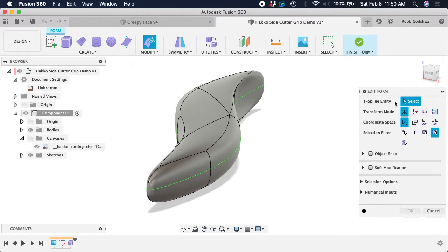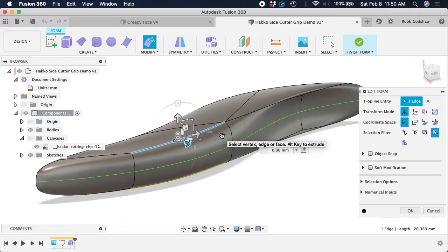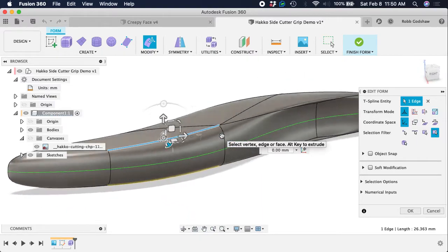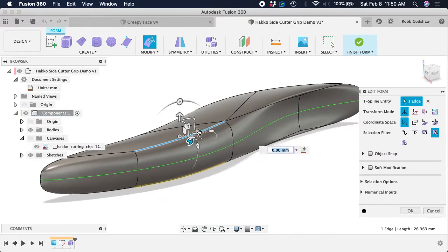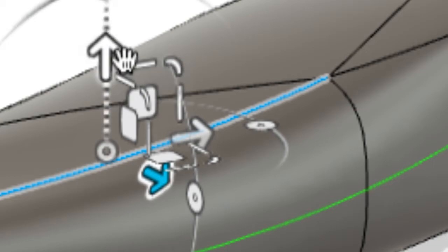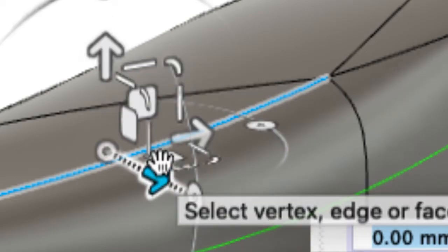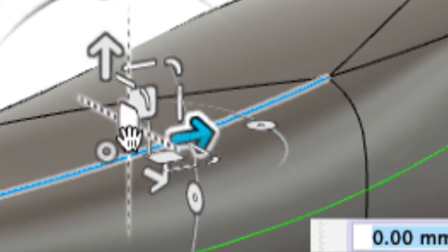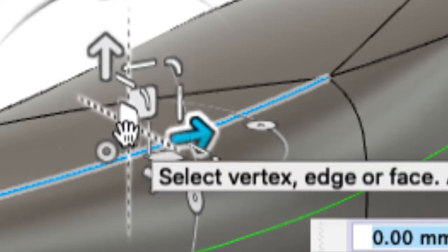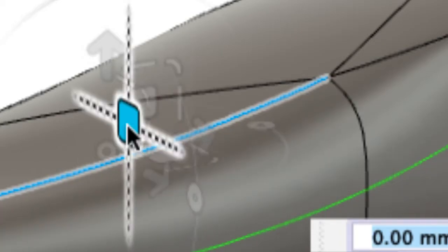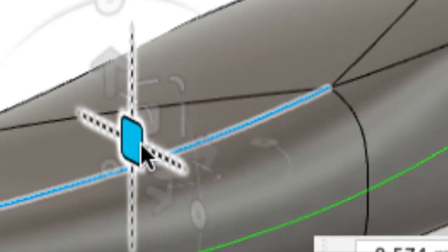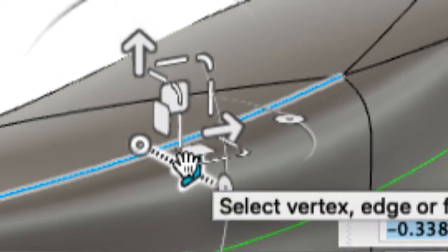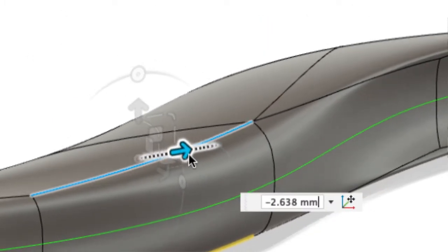So the modify tool lets you grab either vertices, edges, or faces, and lets you move them, rotate them, or even scale them, which is kind of weird, the scaling especially. And this little gumball widget here lets me move it in one direction, another, and the third direction. These ones let me move it in 2 directions at once. You see how when I mouse over it, it jets out these little crosshairs. That can be useful. These just let me move it in one direction.